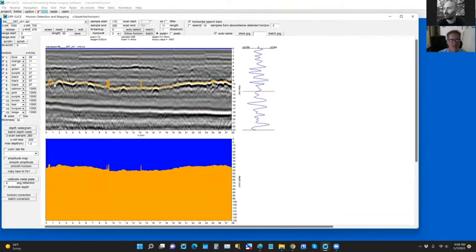And you can see it did a reasonable job on detecting the horizon here, but there are a few areas where it lost the horizon. It could be missing. We have what's called a moving filter, and you can set a filter length. Right now it's set here to like 11. You could put a filter length that would take the moving average and reset anything that went above a threshold of 1 sample back to this moving average. So if we run that, we could do something like that. And that looks like it has a nice detection on there.